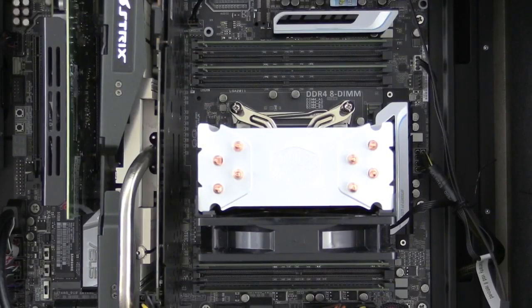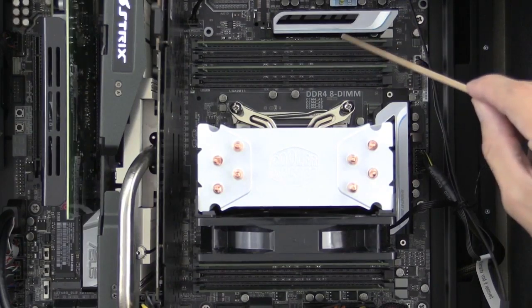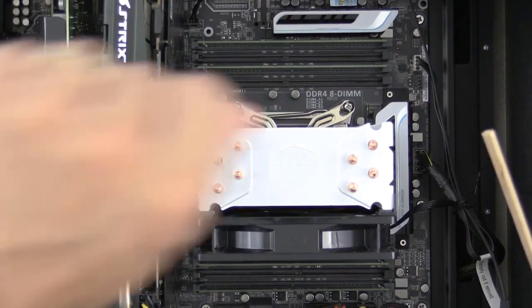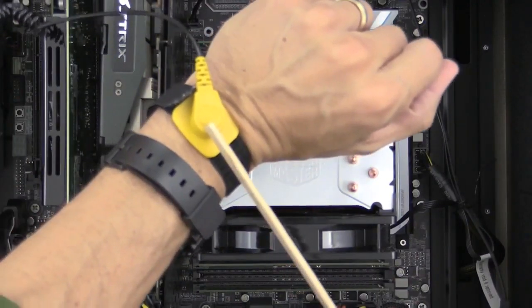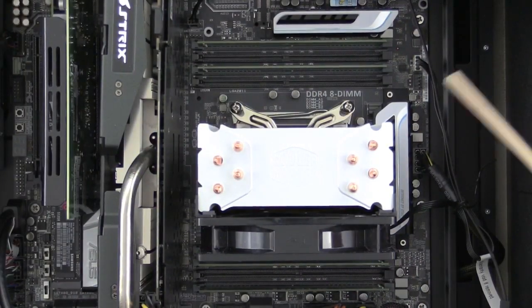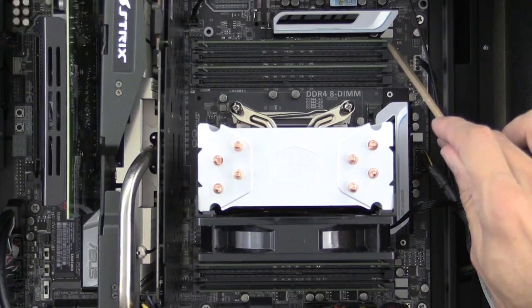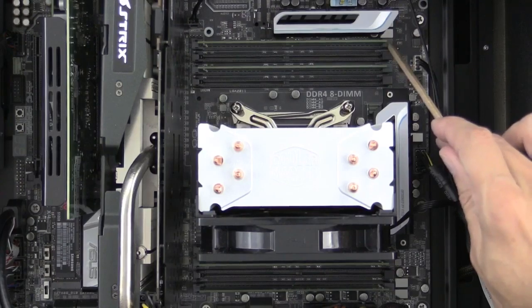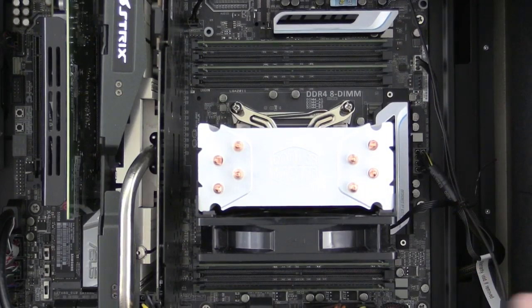Okay, so we have our computer here, and I've taken the case cover off, and you can see inside, and here is our RAM. We've got 1 stick, 2 sticks, 3 sticks, 4. These are going to come out. Now, before you do anything, you want to make sure you have your anti-static protection set up, which we do. And these are easy to take out. You need to release them by pressing to the side with this ear or lever or lock, whatever you want to call it, tab. And so we'll do that for each of these.